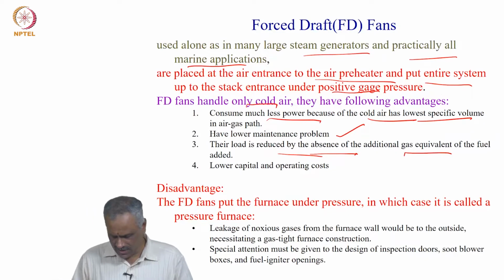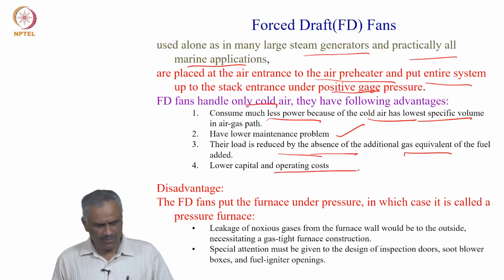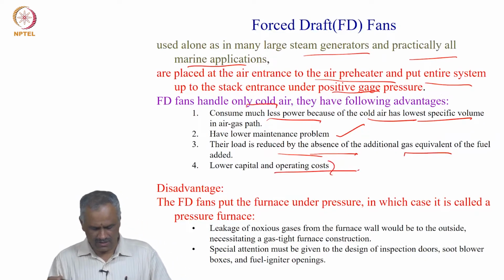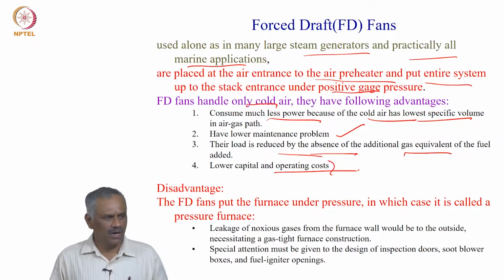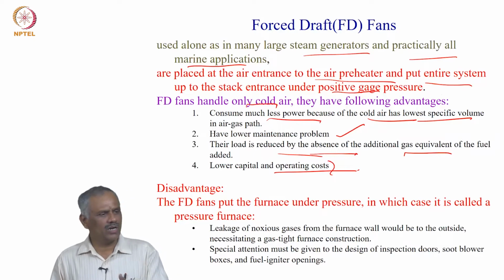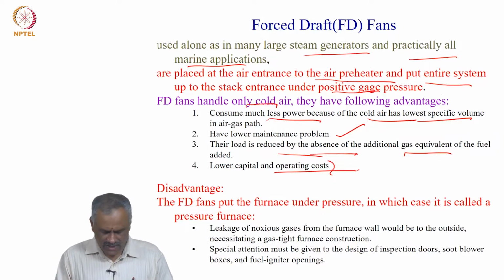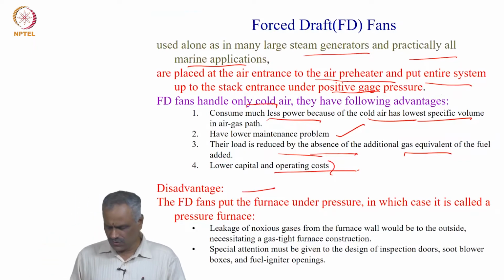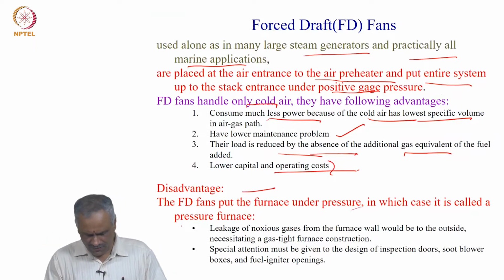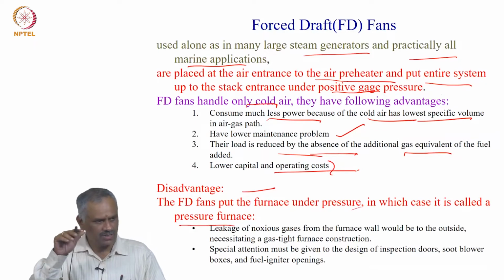It also has lower capital cost and operating cost, because it is handled cold. See, operating something in cold condition is different from the hot condition, so cold condition is always simpler. The disadvantage mainly here is that it is pressurized, so the furnace is under a pressurized condition.